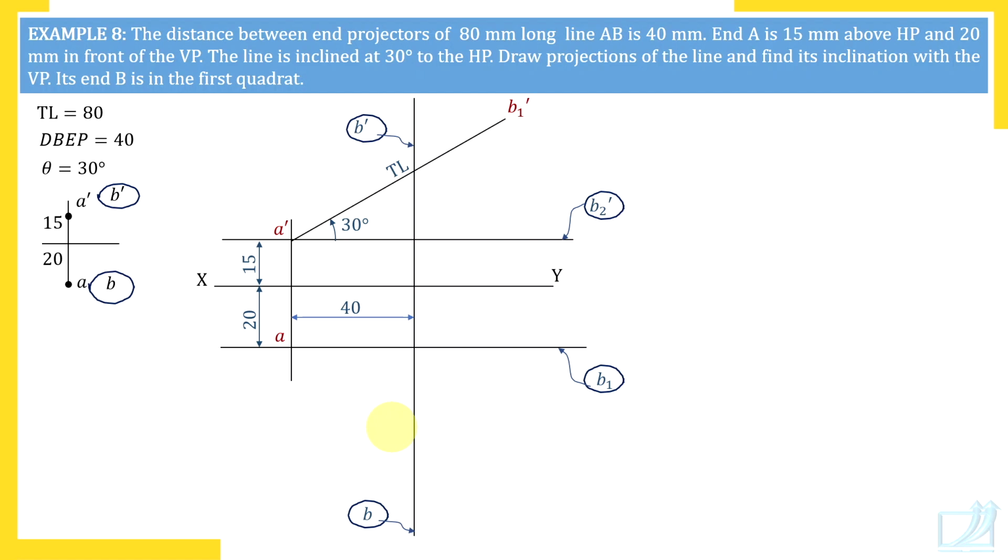Through that point, again you should draw horizontal vertical lines, and when you are sure that there are horizontal vertical lines through the new point also, then use compass again if required. Okay, that is our procedure properly. So through B1 dash, I'll draw horizontal line and vertical line. So through B1 dash vertical line, which other point on this line? B1. So here it is B1. There is already a horizontal line we have drawn for B1. So we know where exactly B1 is. And AB1 is always PL.